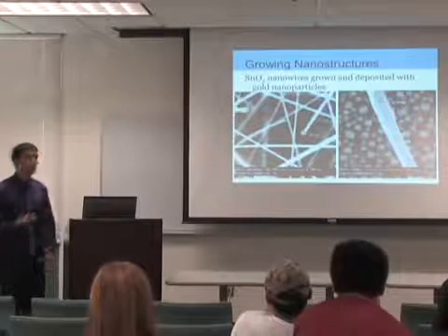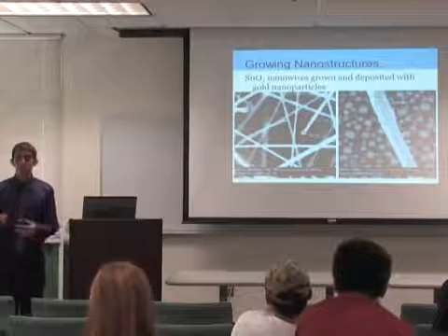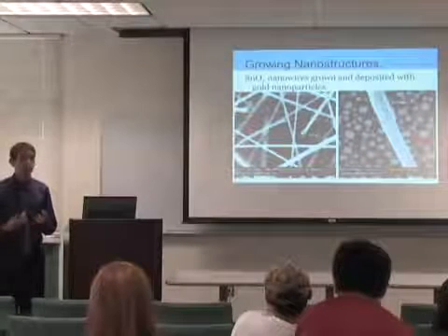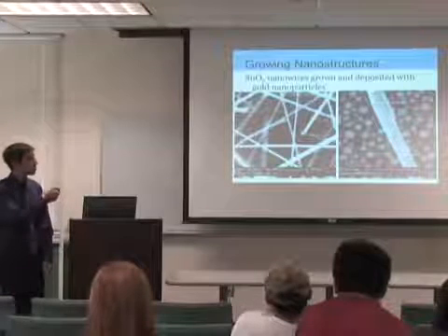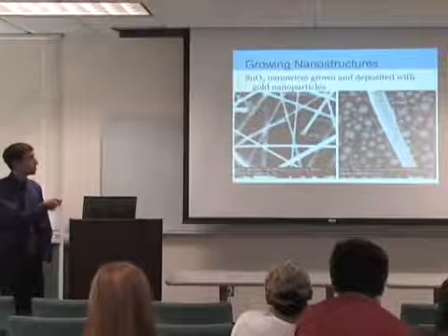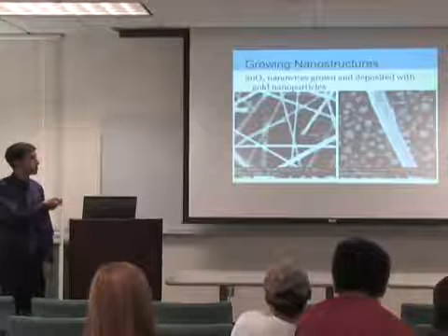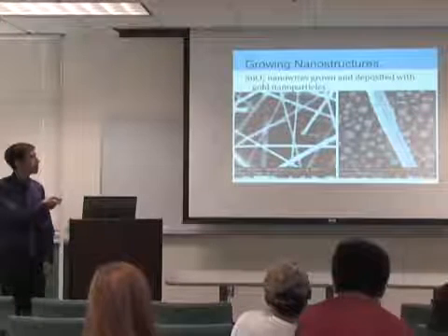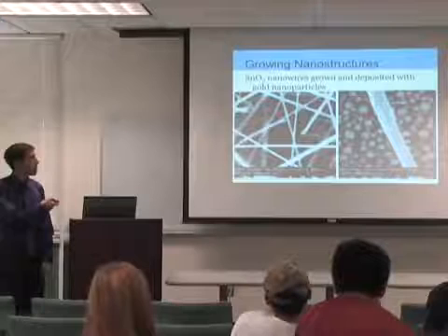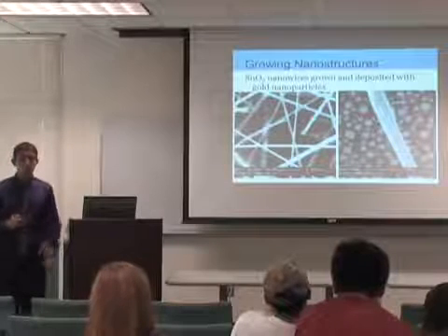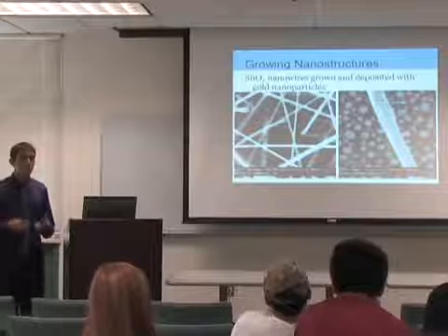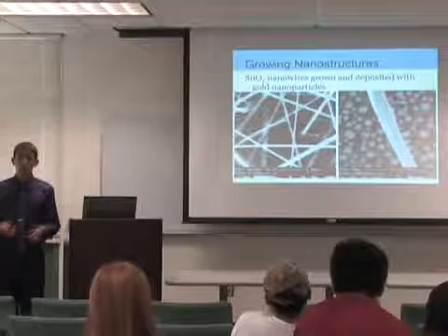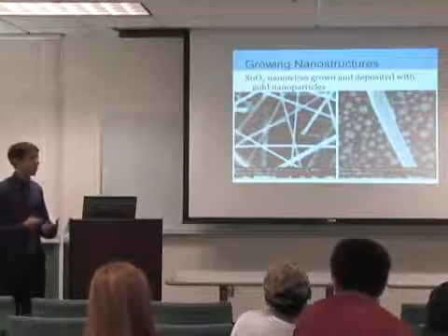And second, these nanowires are very easily reproduced, which is incredibly important because we need to be able to make devices with these nanowires. Here on the right, you can see another scanning electron microscopy image of a single tin oxide nanowire covered with gold nanoparticles. These gold nanoparticles range from around 25 to 50 nanometers in diameter, which is just optimal for the surface plasmon resonance that we hope to see in these gold nanoparticles.